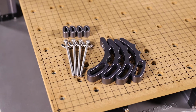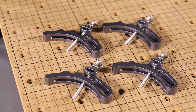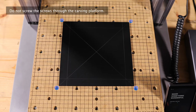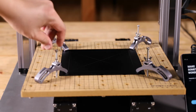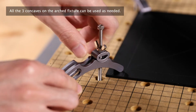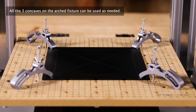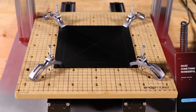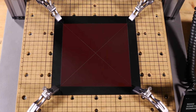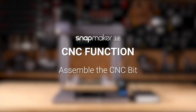Third, assemble the clamp sets. Take the presented accessories, then assemble them into 4 sets of clamps. Fourth, position the clamps. Place the material at the center of the platform and choose the proper screw holes to fix the clamp sets. Fifth, fix the material. Firmly put the thinner side of the arch fixture onto the material and fasten the wing nut. Follow this step to fix the left clamp sets. But to avoid collision, it's important to prevent the clamp sets from extending out of the platform or overlapping the largest possible carving area.